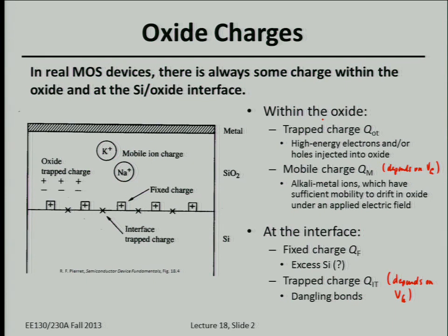Okay, so the easier question to ask, like if electrons get trapped due to dangling bonds at the oxide interface, why don't those electrons just go into the oxide? Well, there's a big potential barrier, right? The 3.1 eV kind of potential barrier for electrons. Okay, so in the oxide, there's a huge energy band gap. So technically, that means no. Oh, okay. So that's a good question. Okay, so, energetically.